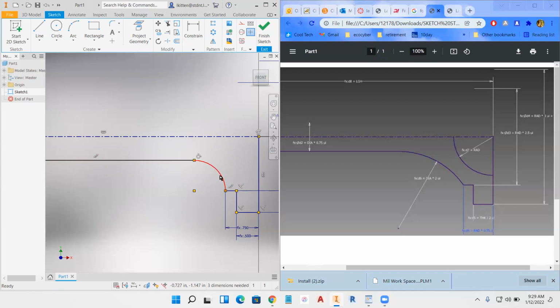It's showing a parallel, and it's not showing that it's doing that, but it's forcing it to happen. And I can't get it to not do it, probably because this point on this quadrant is vertical with the center point here, even though it's not supposed to be. All right, so the way to fix that is not too bad. If yours is going straight up and down, we're going to have to fix it because it's not supposed to be straight up and down. So I'm just going to delete that arc because it failed miserably.